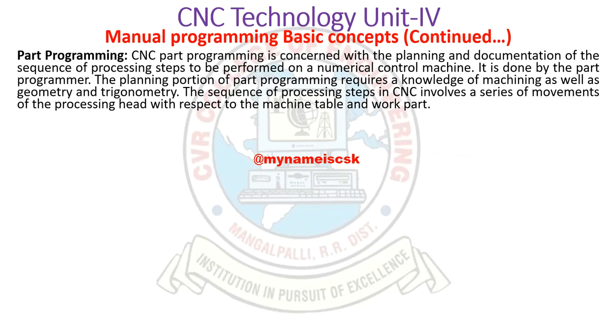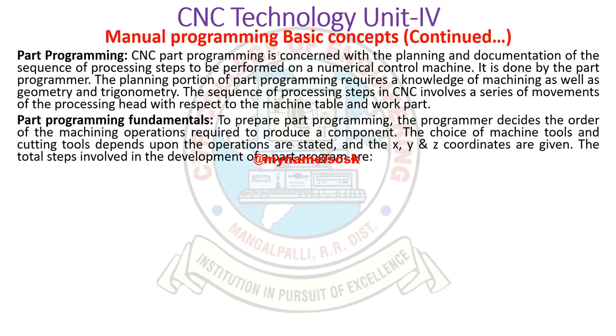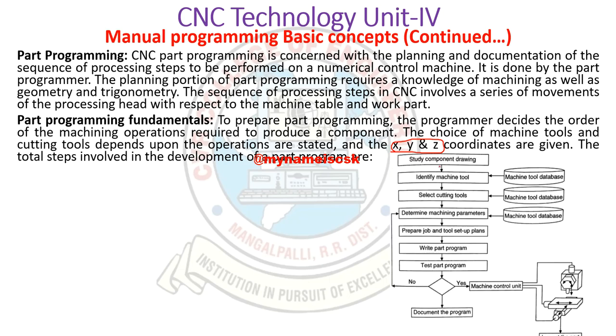Next, part programming. Whenever you are learning CNC technology, you compulsorily have to learn part programming. It involves the following. First, you have to know the part programming fundamentals, whether you are giving XYZ or any other coordinates. The first thing is we have to study the component. Whatever we are manufacturing, first we have to know the drawing of the component.